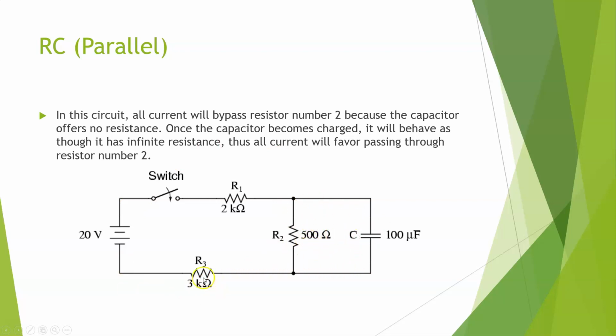It's out. It's done. And all we have here is a continuous loop. Why wouldn't the current flow down this wire? Because it gets to the switch and it's broken. Why wouldn't it flow this way? Because it gets to the switch and it's broken. But it can flow in this square over here. So if we opened up the switch, the capacitor would naturally discharge through resistor 2.